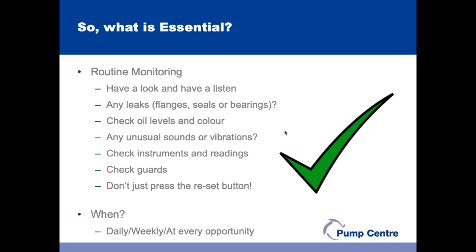And I've put a final thing there, which is not really routine monitoring, but it's a really important point, which is that there are many instances where reset buttons have been reset and pumps have been restarted, and somebody walks away thinking that's great. But there are many instances where reset buttons have been repeatedly pressed without looking into the reason why the pump tripped in the first place.